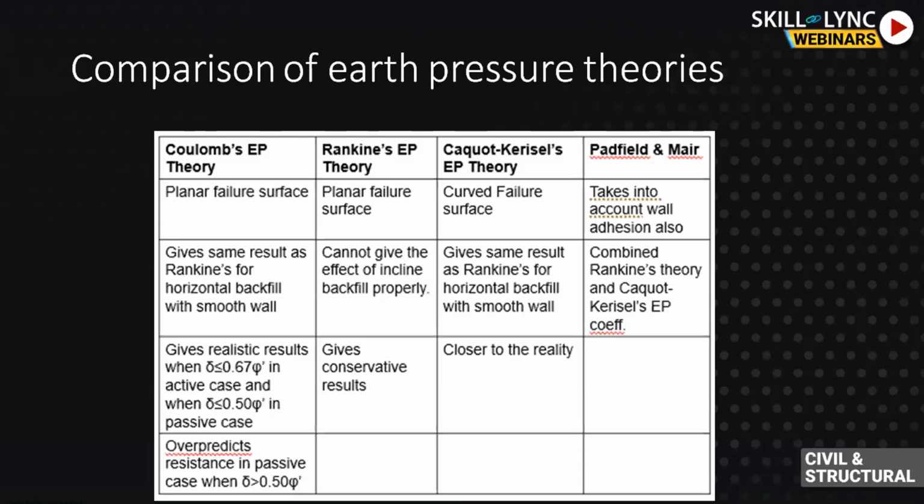The second most common we use is Coulomb's theory. This is like when a retaining wall prevents a wedge of soil from sliding down, an assumed slip surface is determined. This is usually assumed to arise from a stress that increases linearly with depth. The limit obtained will prevent sliding, and the slip surface assumed is used in the calculation. But sometimes this can also be an unsafe condition.